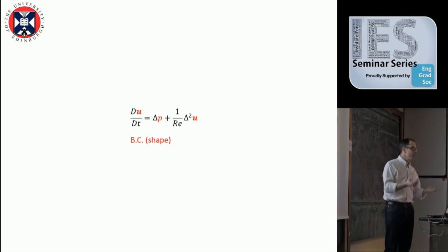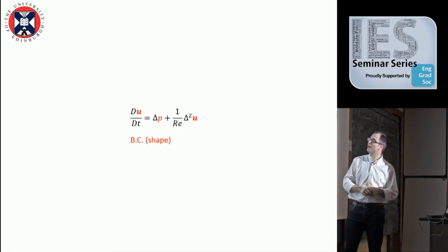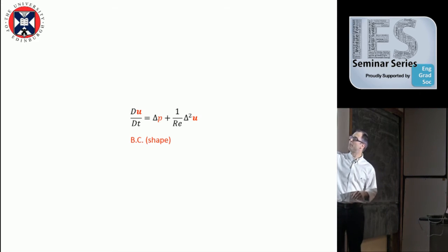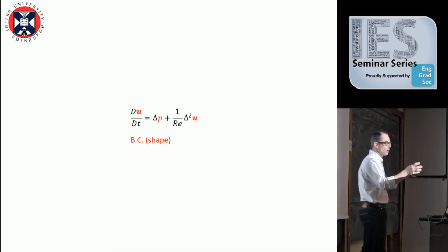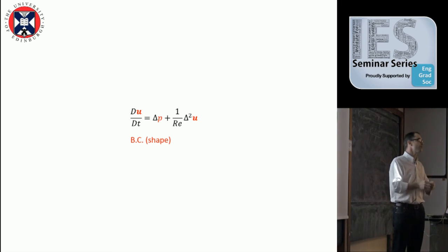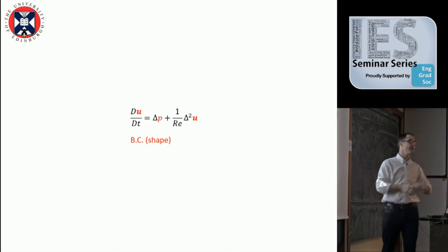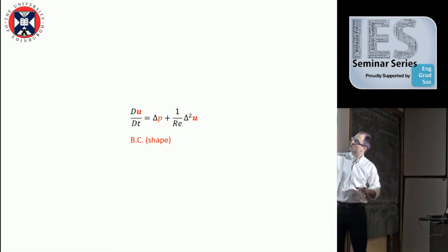Now, if we make it non-dimensional, the same exercise we did before, it is very interesting because now this velocity is a non-dimensional velocity. It's the ratio, for instance, of the velocity wherever you are to the velocity at which the airplane is flying. So this is a non-dimensional value, this is a non-dimensional value, and this too. And what you observe here is that there is only one parameter that comes out, which is the Reynolds number.